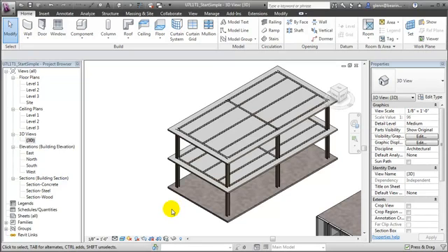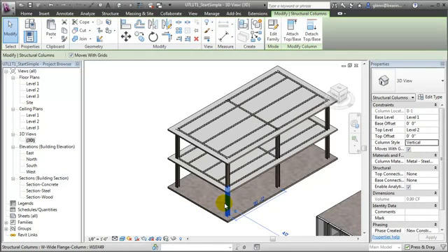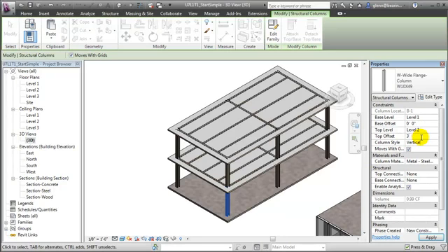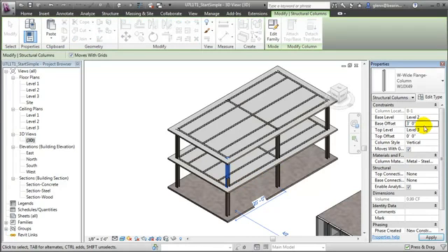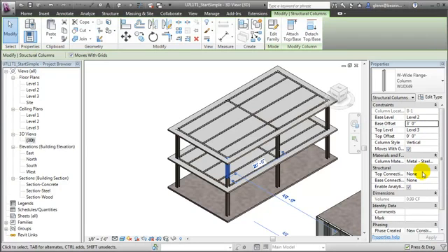For example, in a steel frame building, the columns typically don't run from floor level to floor level. To facilitate easy joining of the column elements in the field, the tops of the columns will actually be offset above the floor level, say 3 feet, where it'll be easy to join them. To compensate for that, the columns on the second floor level should have an equivalent base offset. So again, entering 3 feet to put the join in the proper place. We should repeat this for all the column elements.